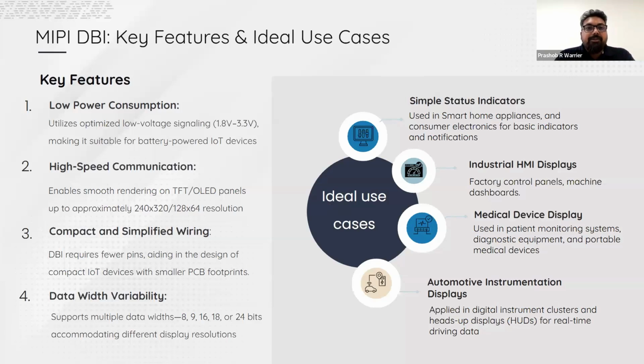This particular interface is very power efficient since it uses a voltage of somewhere around 1.8 to 3.3 volts, making it very power efficient for battery-driven applications. And it is also very fast in communicating between the MCUs and the display. It can communicate with TFTs, OLEDs or LCDs, for example at an approximate resolution of 240 x 320 for the TFT, and for OLEDs something like 128 x 64 resolution, which can be used for very compact device designs.